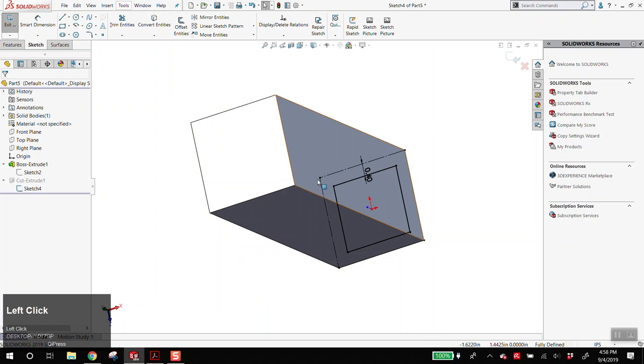So I'll try and say it a different way. We copied the original sketch into the new one because we want that original sketch to drive the size of the hole. The reason we made it construction lines is because we're just using that sketch for reference. We don't actually want these lines to be cut or anything.